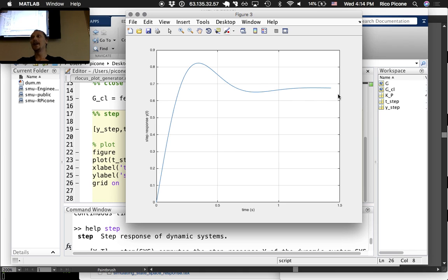The way that we would fix that, if we were using PID control, is to add an integrator to it. An integrator would help the steady state error that we have here. This is like 32% steady state error. Not great. Not really what we want.